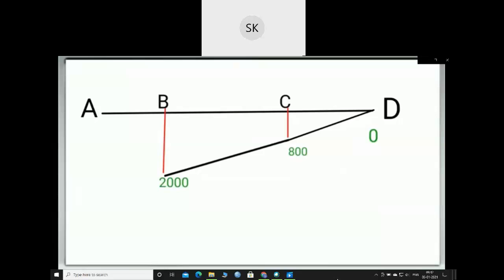The bending moment calculated at point A is equal to minus 2700 Newton meter. So we will mark this point below the baseline as 2700 Newton meter to some scale and join these 2 points by a straight line since AB follows a straight line rule. Now, enclosing the diagram by joining these 2 points, we will get the resulting bending moment diagram.